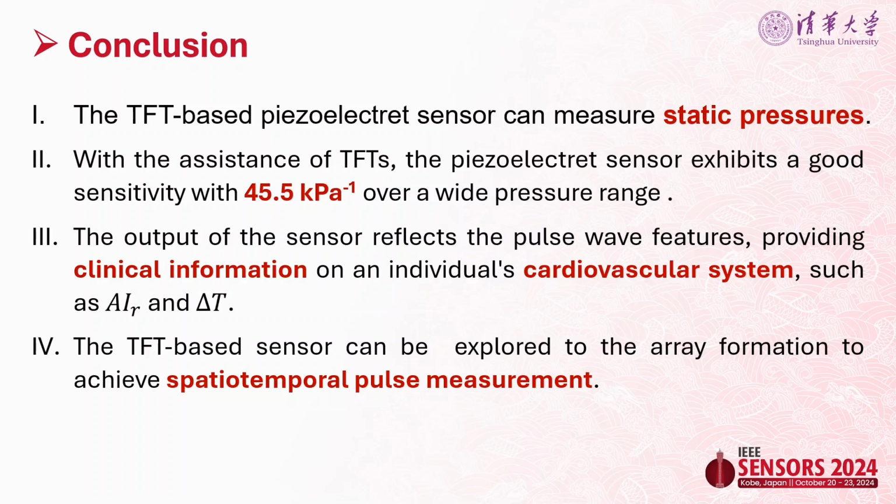With the assistance of TFTs, the piezoelectret sensor exhibits a good sensitivity over a wide pressure range. The output of the sensor can reflect the pulse wave features, providing clinical information. And the TFT-based sensor can be extended to the array formation to achieve spatial temporal pulse measurement.